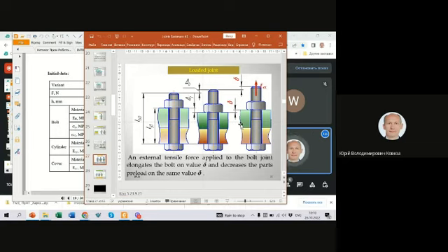After that, after pre-tightening, bolts start operation in a load conditions we have. And under this load, bolt elongates one more on a delta, and the same delta is a result of decompression of joint.